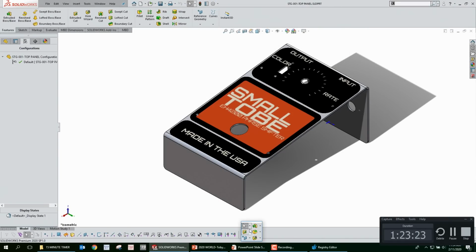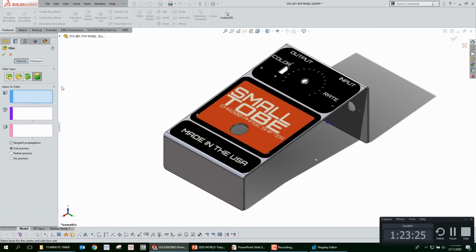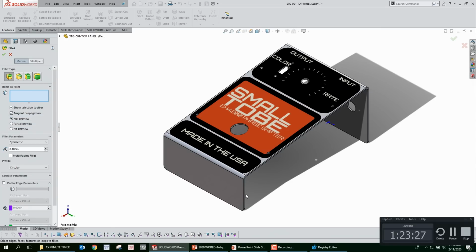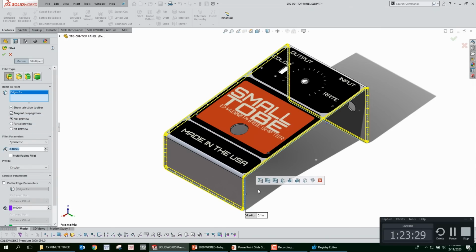Control brings it back. So if I go here to fillet and I single click this edge, and then this menu comes up, and then I move away, and it goes away, can we bring it back? You have to go back kind of near where it was before, and then press Control, and it'll come back sometimes. I've had this happen too. Usually what I do is I just unselect the edge and then select it again. But yeah, I've seen that too, where you move away and it goes away, and you come back and press Control, but you can see it's not happening here. Question?